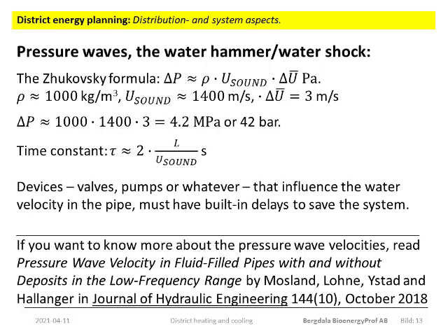But the fact that the sound velocity appears means that the occurrence of the pressure shocks has something to do with time. If the pressure wave bounces back and forth between the ends A and B of a pipe that is L meters long, then the time for the shock wave to go from A to B and come back to A again will be the total length traveled divided by the velocity. Changes in the water momentum, like velocity changes, shall never ever be faster than this time constant.